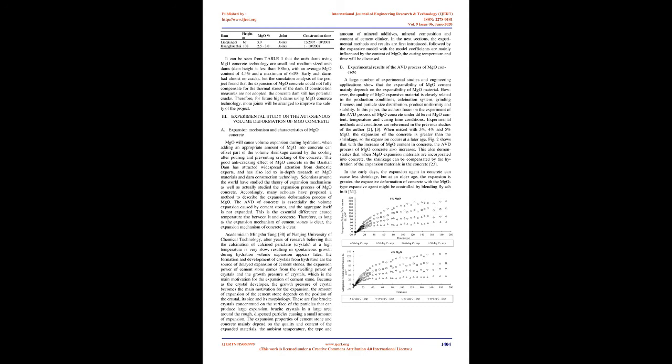The expansion behavior depends on many parameters including its reaction activity, dosage, mix proportion of concrete, curing temperature and age, etc. According to the previous statement, traditional techniques for controlling the temperature rise of concrete have been developed relatively. Nowadays, the technology of adding magnesia concrete to construct dams and RCC arch dams has gradually become a research hotspot. So for thermal stress and temperature control, it is necessary to study the AVD properties of RCC mixed with MgO.